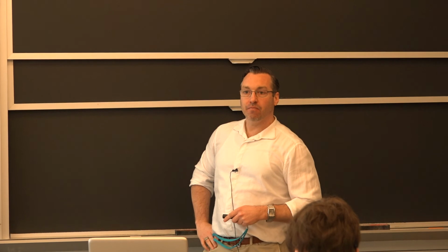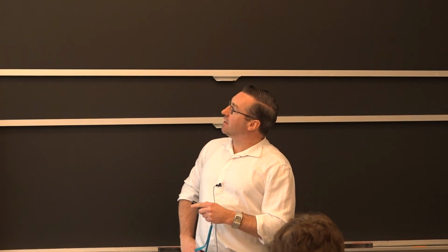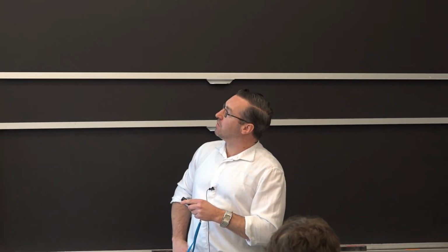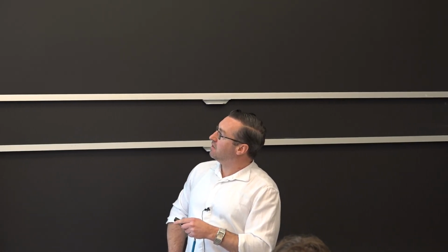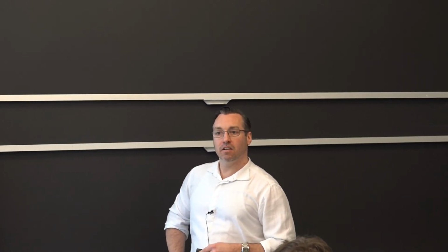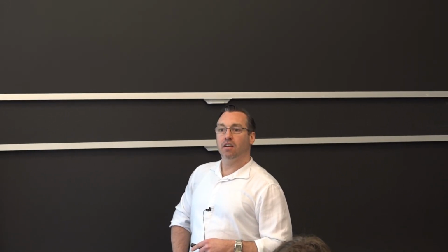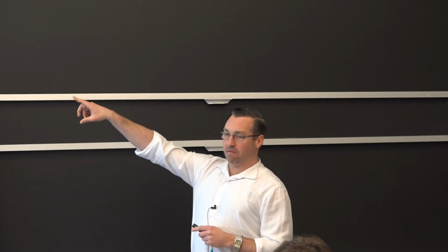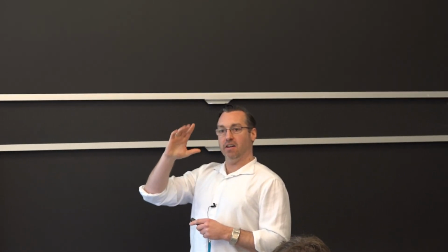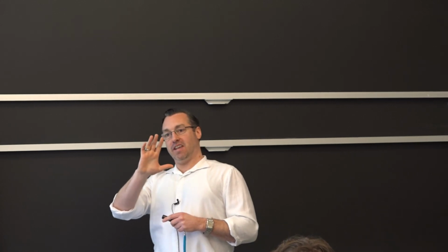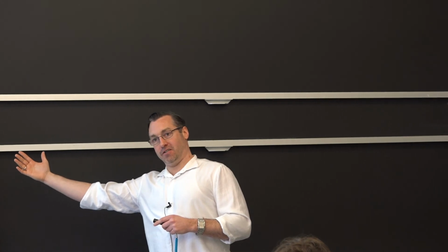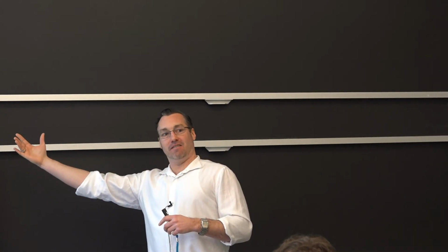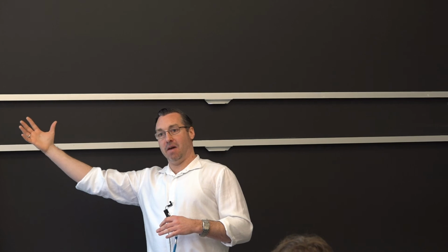I'm sorry, so this is a failure of one of the fan blades? No, this is the disc. This is the disc right here, and these are where some of the blades were still on. These are the fan blades. Yeah, this was the first stage fan. So that means when it became uncontained, since it's the first stage of the fan, it had to go through all the other sections, which means there was a lot of subsequent damage to the engine.